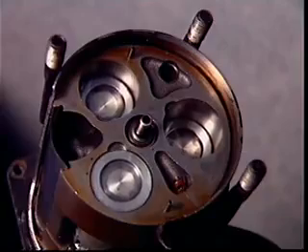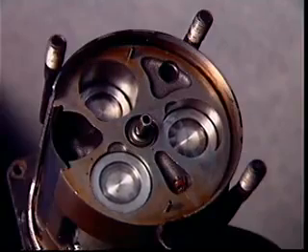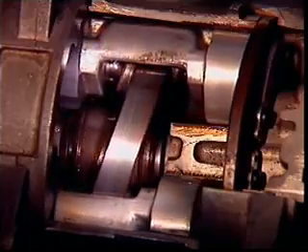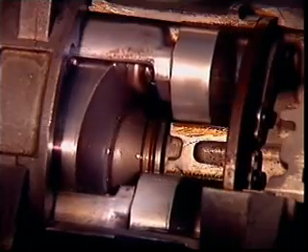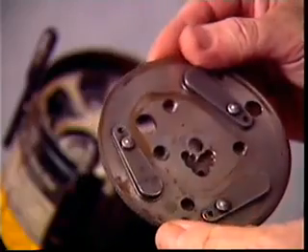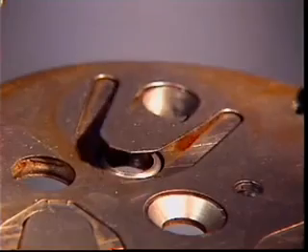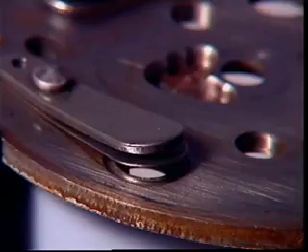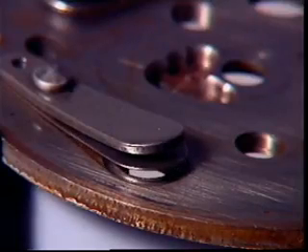The cylinders are placed around the drive shaft and parallel to its axis. Each cylinder has a double-ended piston, allowing a separate pumping chamber at each end of the cylinder. Each pumping chamber has a set of inlet and discharge valves. The inlet reed valves are connected to the inlet port of the compressor by drillings. The discharge valves are connected to the discharge port also by drillings.